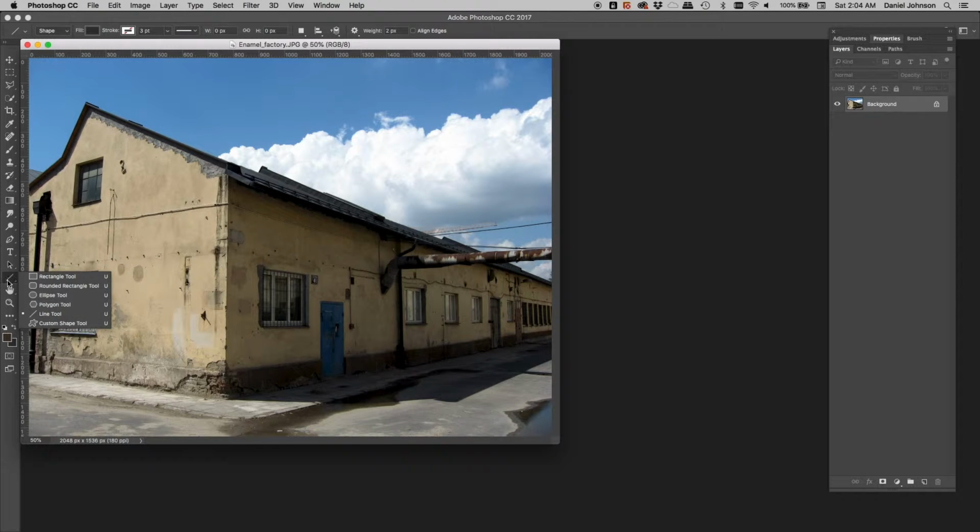I'll right click there. We'll use the line tool, and you want to make sure that your option here says shape. You have the option of pixels, which really isn't very useful at all. And you also have path, which is a vector path, but that's only a start to something. It needs to have something added to it. What you really want to do is a shape layer. This means a vector shape layer in Photoshop. And Photoshop has a wide variety of vector tools, and they're really nice. If you can use Illustrator, you know them in Photoshop. Make sure we say a shape layer.